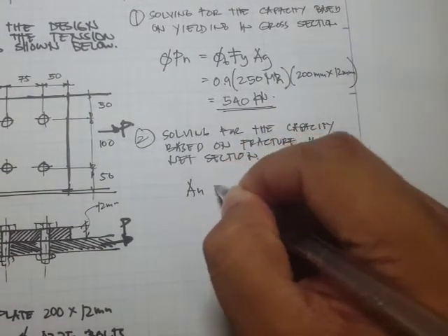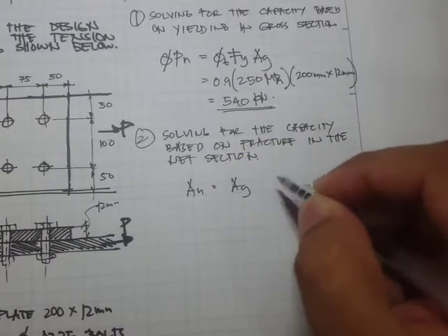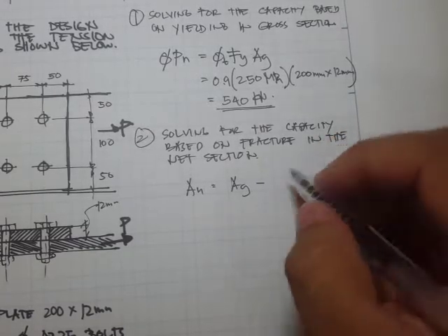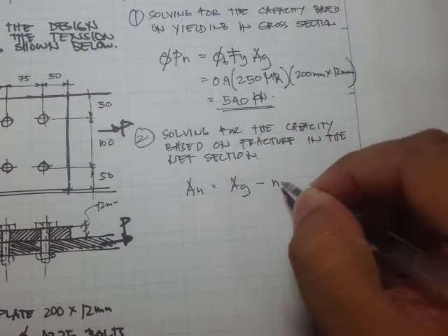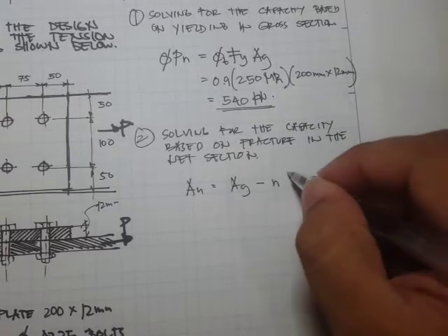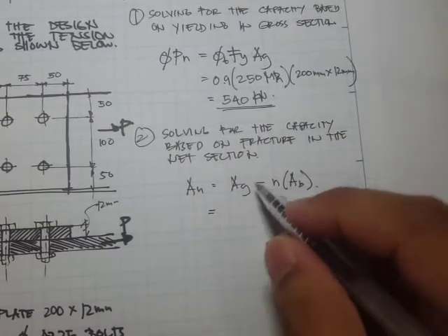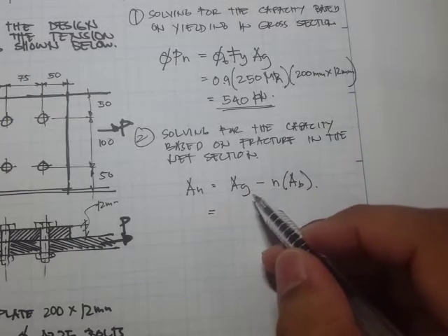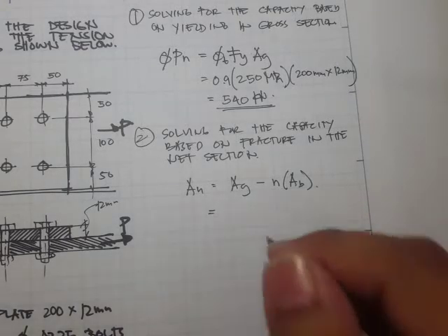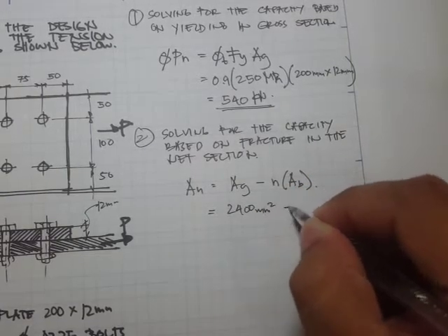So A net is equal to the gross area minus the number of bolts, in that section only, times the area of the bolt hole. What's our gross area? That's just 200 times 12, and that's 2,400 mm squared, minus...